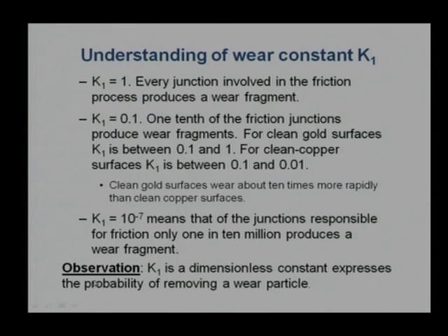What we can conclude from this slide is that K1 is a dimensionless constant. It does not have any dimension, no mm or mm cubed. The way we have treated it, it can be given as a probability of removing a wear particle. We are using a very strong word, probability, but it shows the probability of wear junction removal, or the breakage of the junction with the particle, or taking out the particle and making it a loose particle.